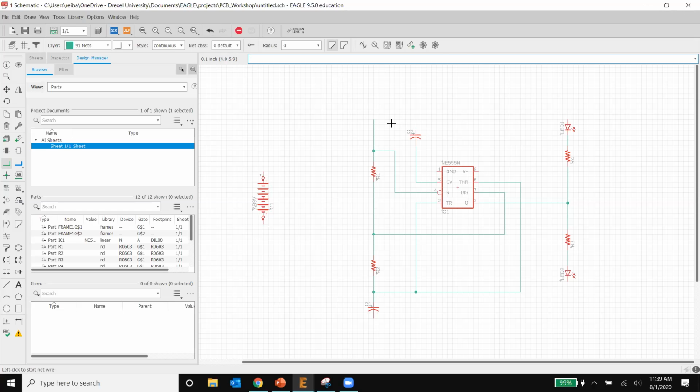I say that because if you use the ground from the library, every one of these things means a signal. So if you tell the schematic that you have a ground signal, it makes it much easier later when you design your PCB, and you're gonna see how helpful it is. So I would suggest keeping it that way.